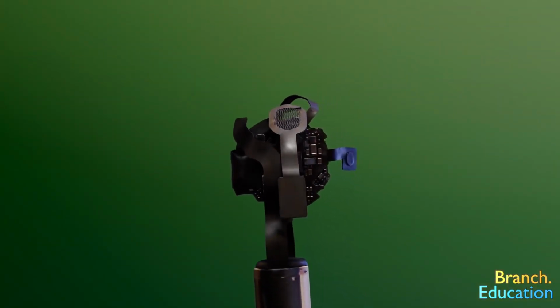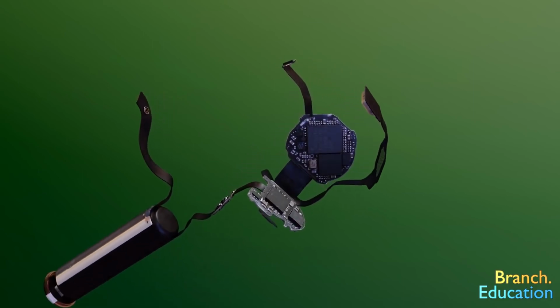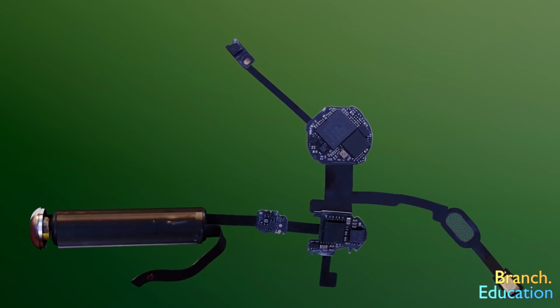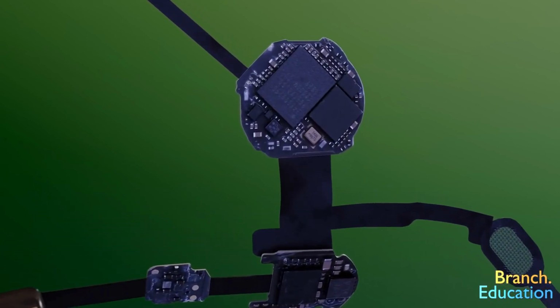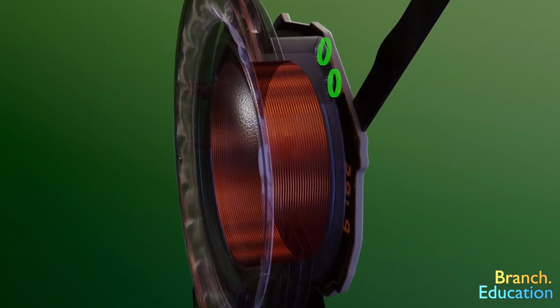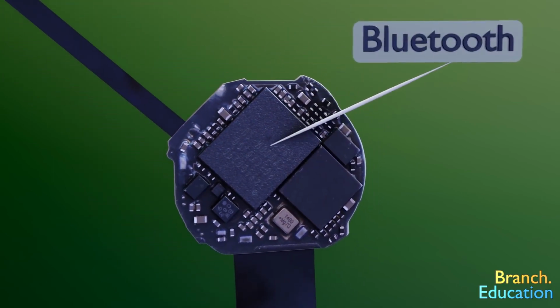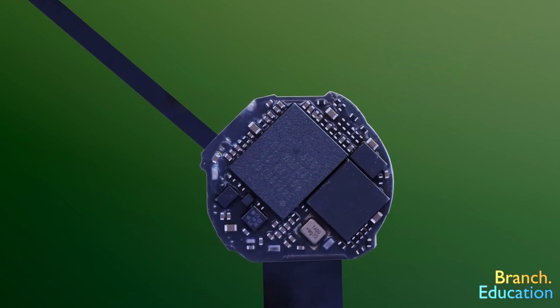This circuitry is essentially 3 separate printed circuit boards, neatly folded into the earbud, with flexible wires connecting them to make a single PCB. On this top board, which is glued to the backside of the speaker, we find 2 points where the speaker connects, along with a larger microchip, which handles Bluetooth connectivity and decodes the compressed audio streams sent from the smartphone.